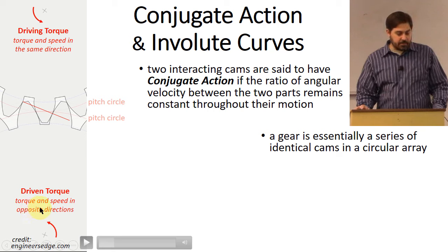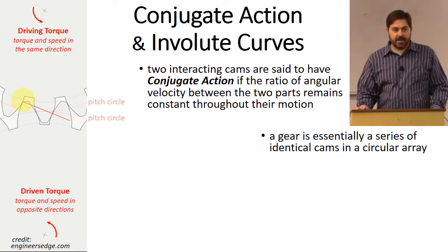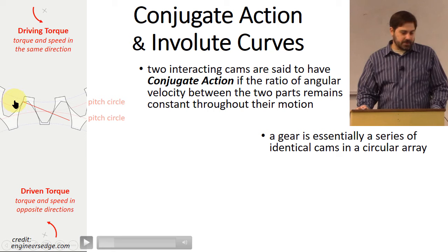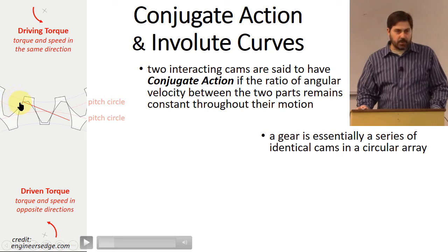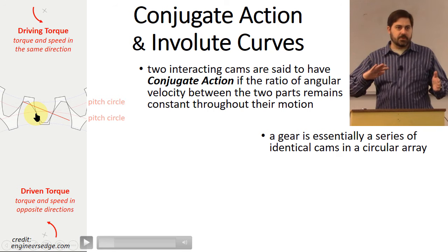This is important because it tells us where the contact is going to happen between the gear teeth. This tooth right here is going to push leftward into this tooth, while this tooth is pushing rightward into this one. So we're not looking at the contact that may be happening over in this other pair, because that's not the direction the torque is biased between the two gears.